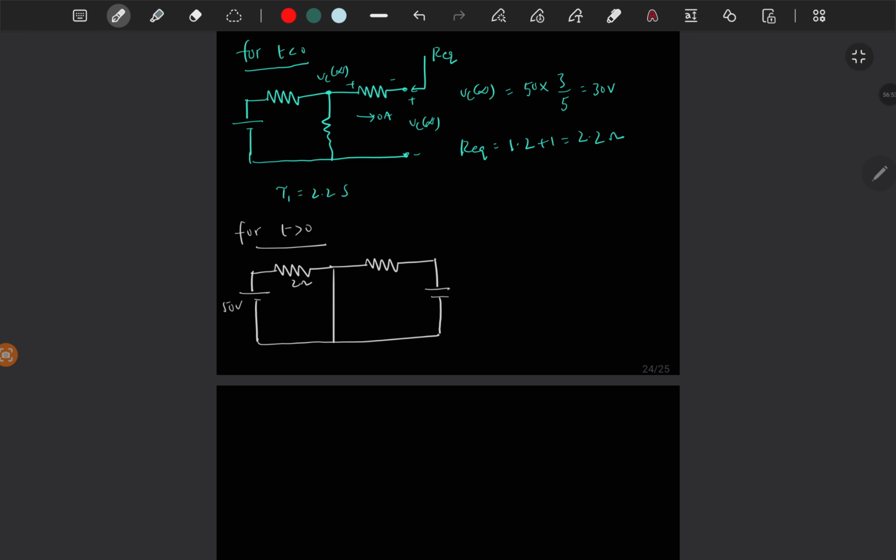See, what will happen to this circuit. Since there is a short circuit, whatever current comes from the input source will directly go through this short circuit. It will not go through this branch, right? So this is 0 amps.